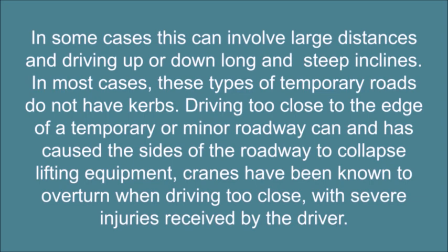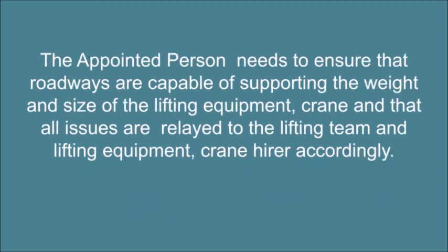Driving too close to the edge of a temporary or minor roadway can and has caused the sides of the roadway to collapse. Lifting equipment, cranes have been known to overturn when driving too close, with severe injuries received by the driver. The appointed person needs to ensure that roadways are capable of supporting the weight and size of the lifting equipment, crane, and that all issues are relayed to the lifting team and lifting equipment, crane hirer accordingly.